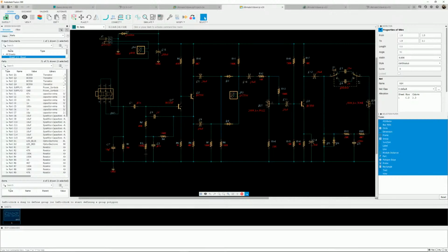And then, so that's a low pass filter. Right, negative feedback, I was going to say it's a low pass filter. Yep. And so the DC bias and the gain is somewhat set by this resistor, and this 47K here is really to provide the DC bias to the base of the front end transistor there. So it's a two-stage inverter, and then off to this one.